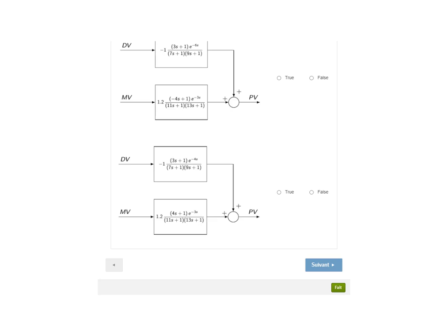Well, let us have a look at the last system. We cannot have any problems with properness. If we look at d over p, the delay in the process is smaller than that in the disturbance dynamics, and here all the poles are stable and the zeros between quotes are also stable, right? They are to the left of the j omega axis, so you cannot have any unstable pole zero cancellations, so here the ideal feed forward is realizable.